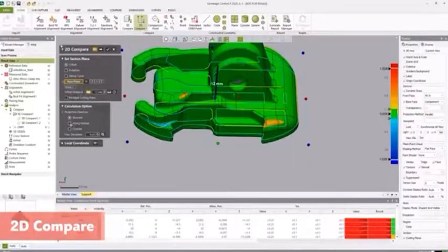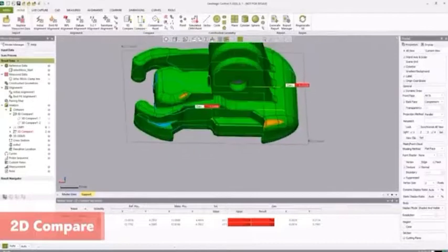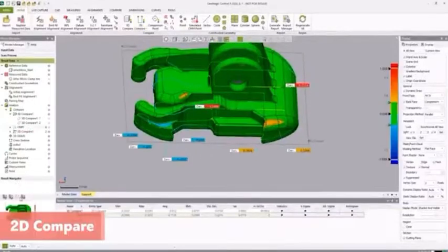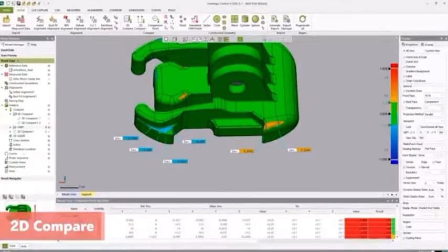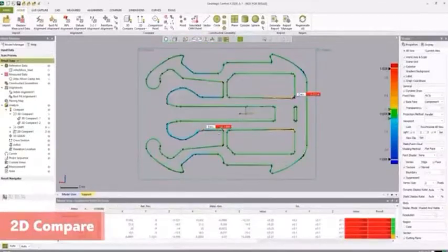Change the offset distance to 12 mm and hit the reverse direction. Click the Next Stage arrow. In the next stage, keep specific tolerance at plus or minus 0.1. Turn on the local averaging tag by checking the boxes next to over and under tolerance count. Click the checkbox to accept. Note that if there are no over or under tags, the part does not deviate from the reference in that direction.